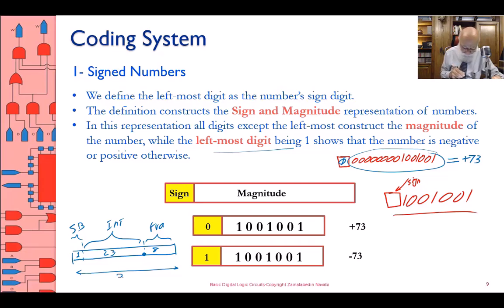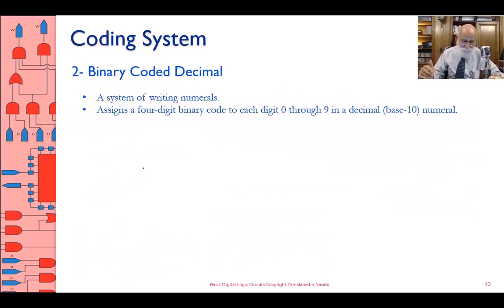And the whole thing is 32 bits. This is fixed point. Fixed point meaning that there is a point, a fixed, imaginary point, where you draw the line between the fractional part and the integer part. All right, so now we know how to represent numbers, positive and negative, fractional and integer.